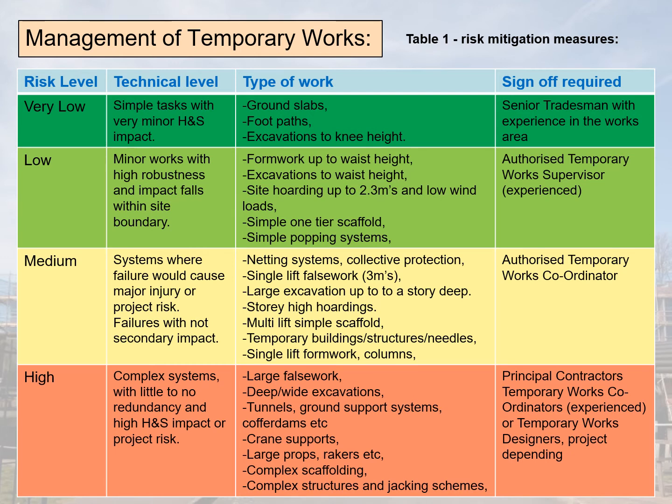As we move into more complex and high risk projects, looking at bases for tower cranes, large falseworks, large needling systems, groundwork supports, cofferdams and so on, and the other areas you can see on the right hand side of the screen, you will normally need the temporary works designer himself or a specific authorised engineer to come in and sign off these levels of works before anything can progress.